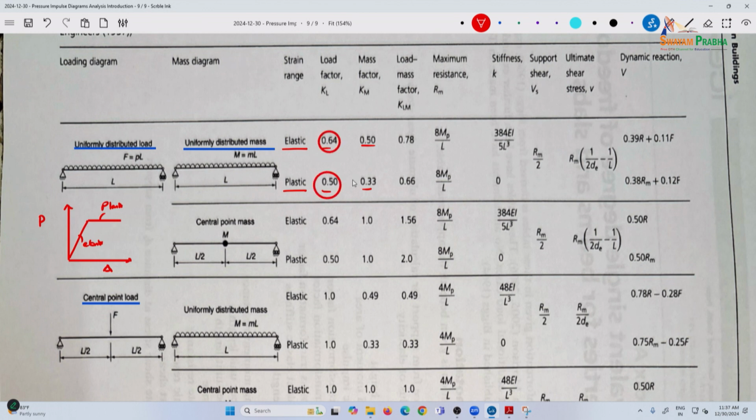How does this come about? You calculate your deflections, for example, and then you compare the two. The stiffnesses in particular. Where's your stiffness, load factor, then there is a load. If you see plastic deformation, in this case the stiffness is 0. And we will talk about this resistance a little bit later.